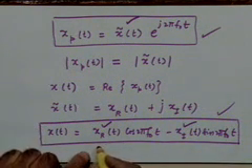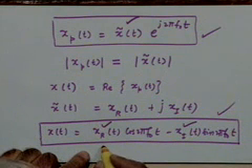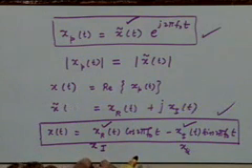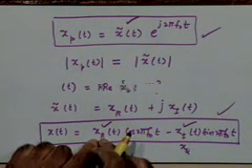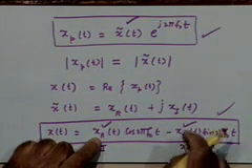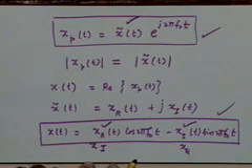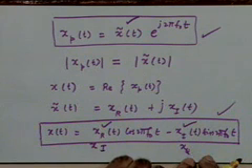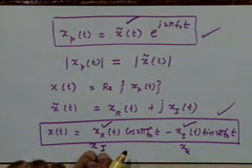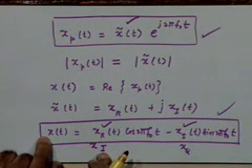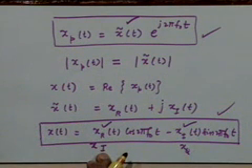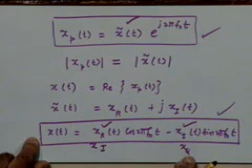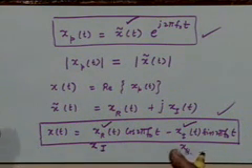Sometimes you will find in the books the notation x sub I here and x sub q here. Here I use the notation real part and imaginary part of x tilde(t), but in many books you will also find the notation x_I(t) here and x_Q(t) here, to indicate that this represents the so called in phase component of x(t), which is a low pass signal, and this represents the quadrature phase component of x(t).